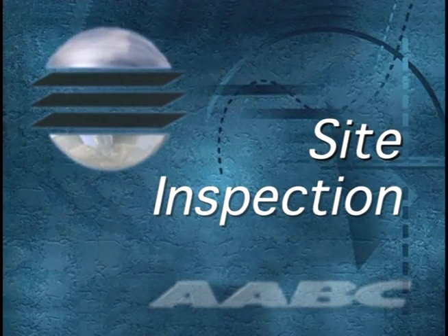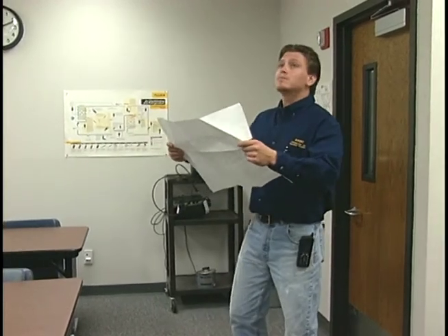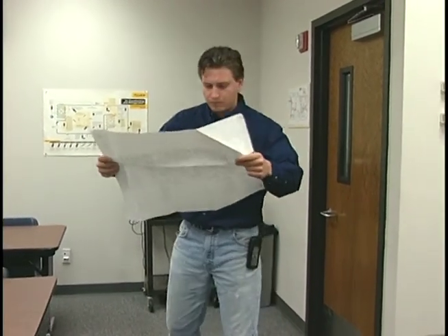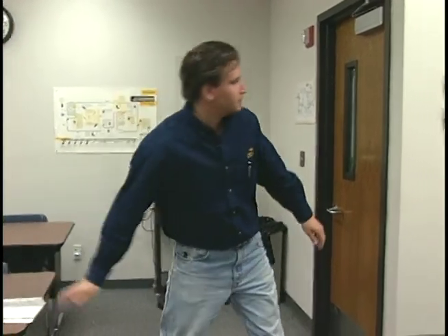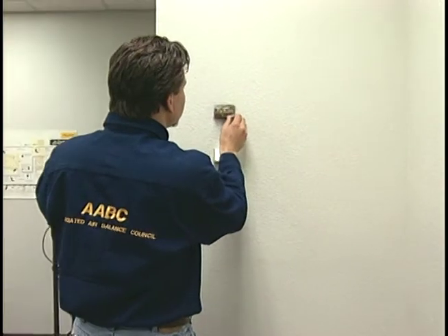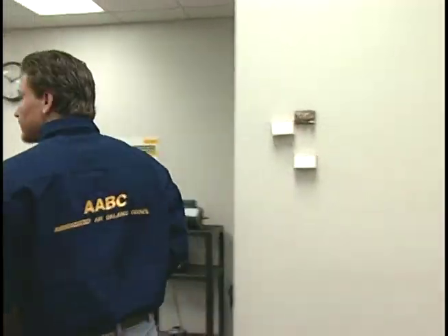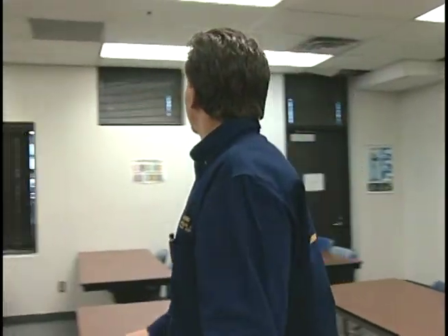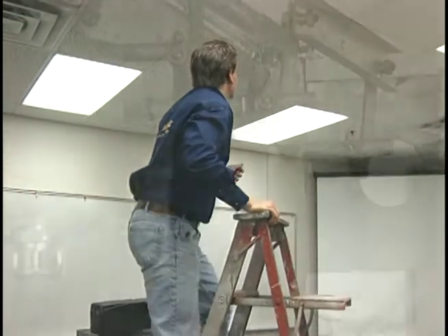Site inspection. At the job site, the TAB technician inspects the building envelope, HVAC controls, air distribution system, and the HVAC equipment. The technician checks that the building's doors, windows, ceilings, partitions, etc. are installed and properly sealed, and that the building is otherwise architecturally complete and ready for air balancing.